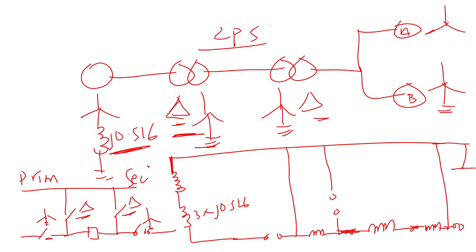A, generator A, no matter where you put it, because they are all in parallel, is not grounded. So you leave this one open, then you draw your line, you leave this one open before you bring the reactance here, and then you bring the reactance of the other one. You connect it to the line because this one is star grounded, right? So we put this together before you come and connect it to this.